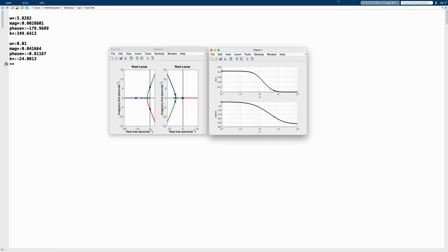And we also know that if we go back a little, we will basically decrease the gain of the controller, and this decrement here will correspond to a certain low zeta value. So we will have a slight angle with the j omega axis, which will correspond to a slight zeta value.